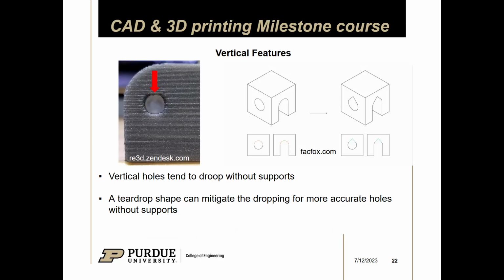One situation that I didn't think about when I first started 3D printing was holes. If you think about a hole and you draw a tangent line along the circle, as you get closer and closer to the top of the circle, you'll eventually get to completely flat, or 90 degrees, right? That's technically an overhang, right? So when you're printing a hole, the top end of the hole is going to have an overhang over 45 degrees. And if you're printing a really large hole, that can typically become a problem and you'll start to see the top of the hole sagging.